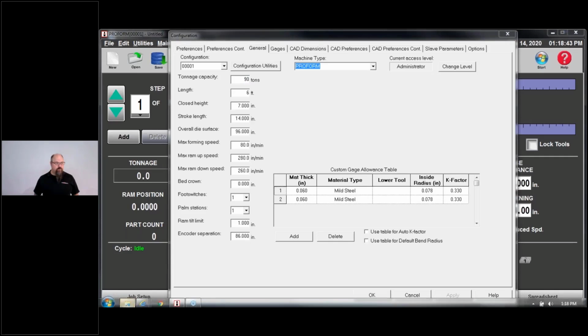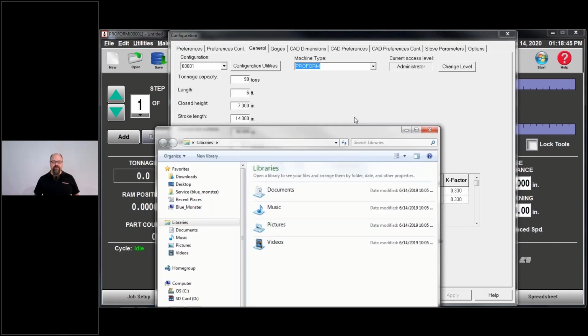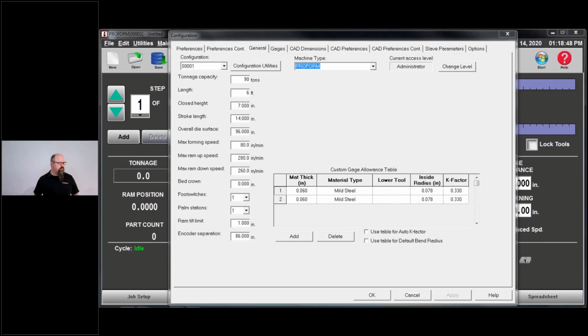files. So, oh, I need to share that. That's not going to work. Yeah, so D, press break, and then you're going to do a search for the actual configuration file. And again, just CFG is the lettering you type in. It'll bring up all of the available configurations. And then as you can see here, I have a whole bunch of different machine configurations from the various customers that I have been to. That's how you bring in your config.